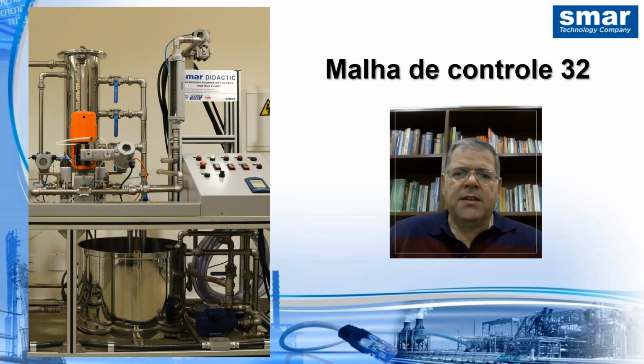Once more, we have an actual photo of the mesh of one. The main tank, the pump will pull. It will pass through this rotameter here on the right via the flow meter. It passes through the valve with a positioner and comes back here or goes to the mixing tank. We have here the consumers where the water can return and close the circuit to the main tank.